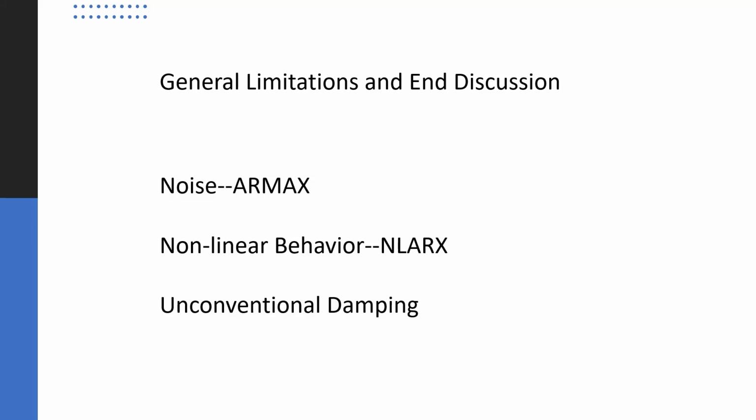And finally, ARX cannot work if the damping of each floor is not proportional to the mass and stiffness of the related story, which means the story has unconventional damping. And these three limitations cannot be solved directly by using the ARX identification technique.